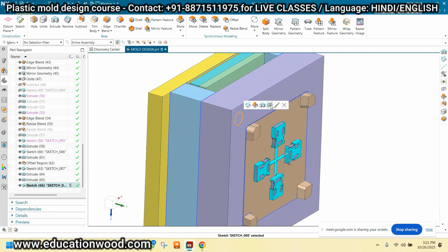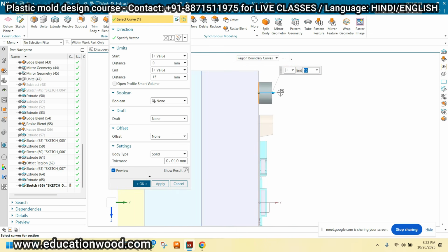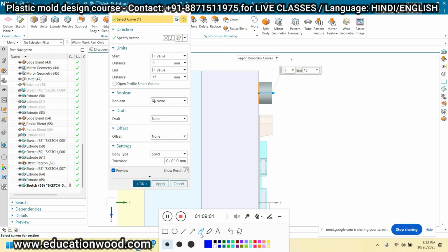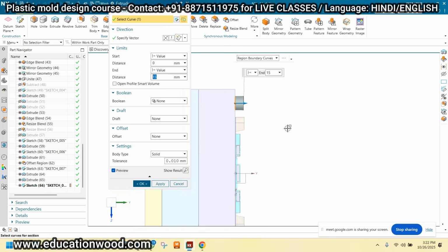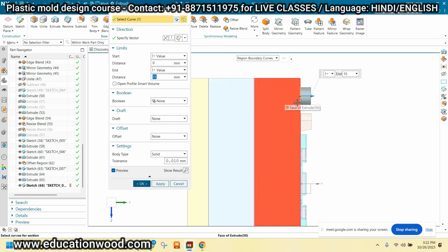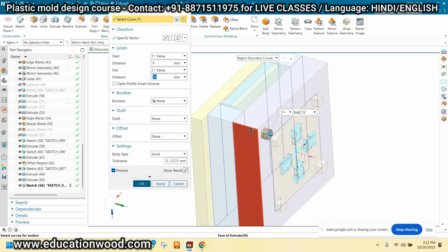Okay, for example, if you have calculated the diameter, you should remember one thing: take the standard guide pillar and guide bush. While you are designing any mold for a customer, you can use the DME standard, the Hasco standard, or any company standard, like the Maruti standard for the guide pillar and guide bush. Any standard you can use, by which they can purchase the standard parts from the market. This is very important.